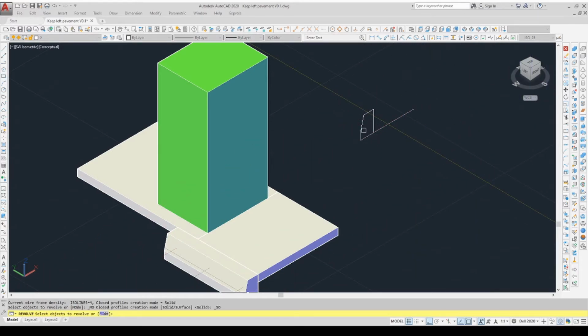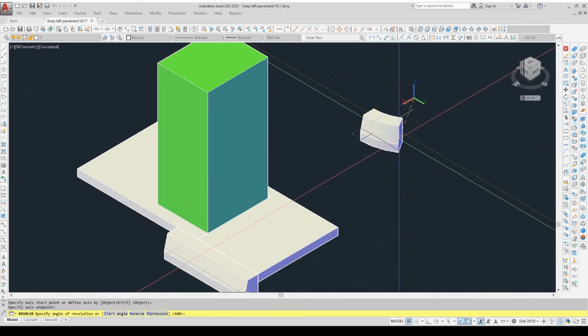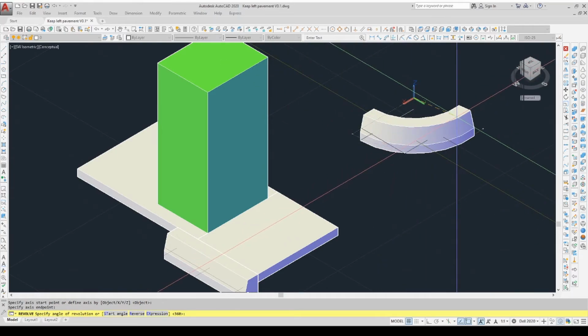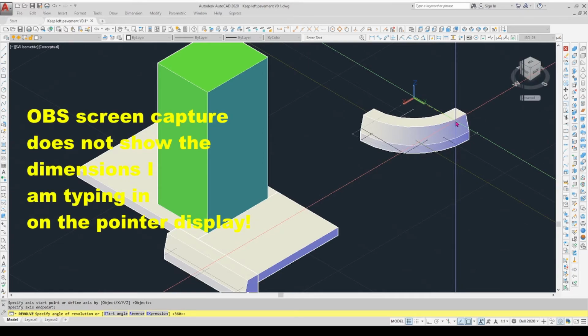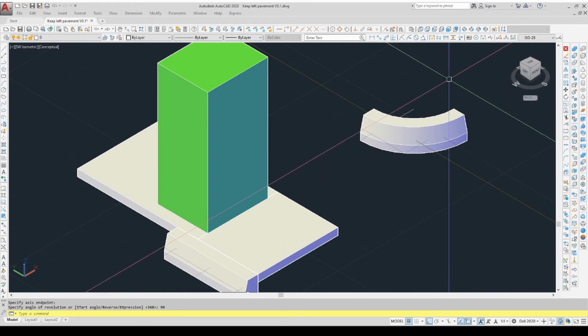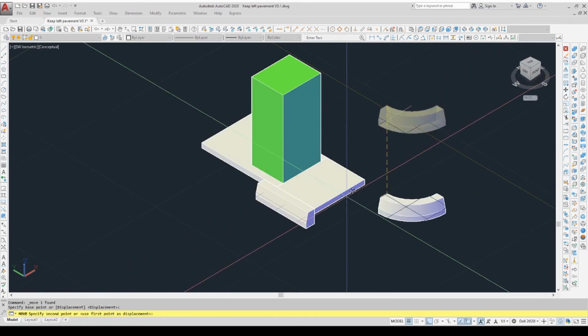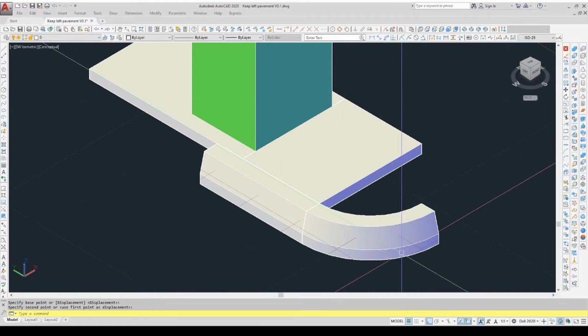So we select the revolve command, we select the object that we want to revolve, we now select the defining point of what we're going to revolve around, and it asks for a second point because you can do things at weird angles. So, I push the cursor vertically above that, and it says, yep, that's in the Z axis. Press return, and hey presto, it will now revolve it around that 12 inches away point into a curved thing. As you can see there, it's showing me the degrees. So if I type in 90, we would get 90 degrees. That's about as big as they make them. I don't want 100, I want 180, but it wouldn't be made as 180. So I could then move that from there to over here, and I've now got my curved stone.